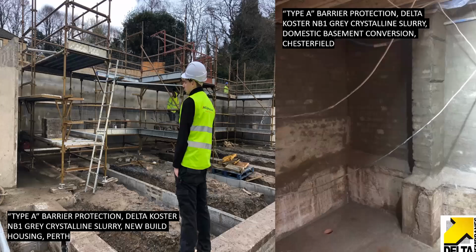We can't put type A products on the outside of the building because it's existing. That's a very good argument. We can't dig it out of the ground and waterproof it on the outside. We need products that are going to be capable of withstanding pressure that comes through the existing structure. So now we're into type A cement-based slurries, okay, crystalline slurries, multi-coat renders, repair mortars, things like that.